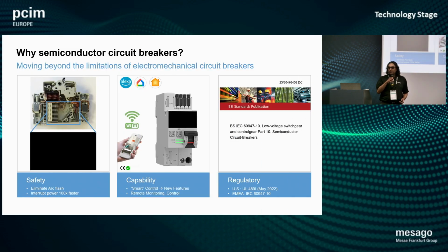There is a tremendous amount of activity happening around the world today in semiconductor circuit breakers. These are fundamentally more reliable. They don't suffer from arcing and failures related to arcing. They have much faster reaction time, so they can limit the overcurrent before they actually turn off. That's a big advantage which they bring. But most importantly, when you add these semiconductor devices to connect and disconnect loads, it gives you enough of a critical mass of semiconductors there to now be able to do additional management.